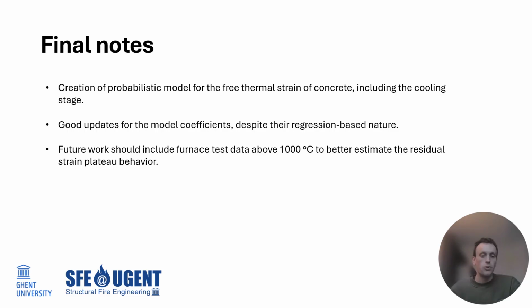And then for future work, we should definitely look at furnace test data that goes to really high temperatures, to 900 degrees, 1000 degrees and above, so that we can get a better estimate for the residual strain plateau behavior.